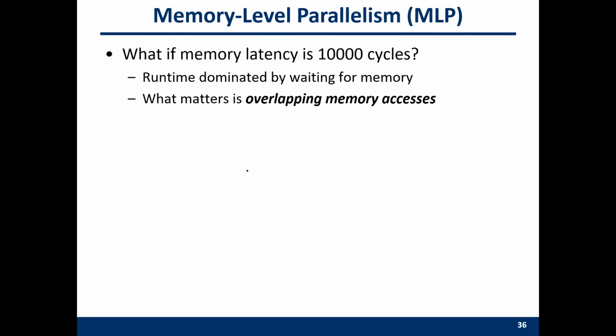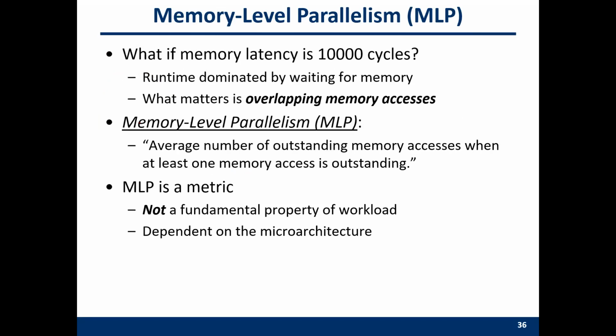So what if the memory is very slow? Then the latency will be dominated by the memory latency. But you can still exploit the bank level parallelism. This is also called memory level parallelism. Memory level parallelism is a useful way to improve your performance.